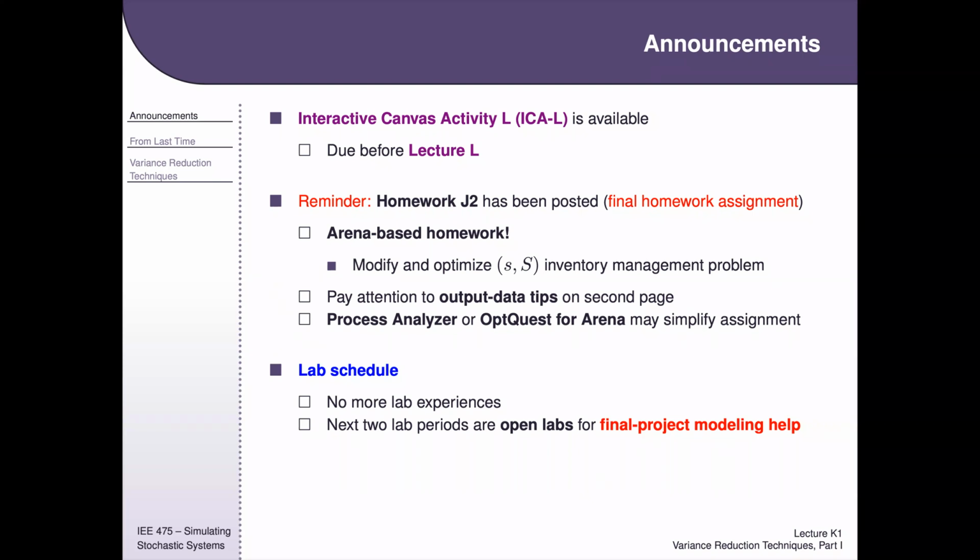There are a bunch of different ways you could do it, but that's where I would recommend you look: the decide block, and the assign statement just as the inventory order is made, and the assign statement just after the order is received and the inventory gets changed. Again, more than one way to do it, but that's my tip for that.